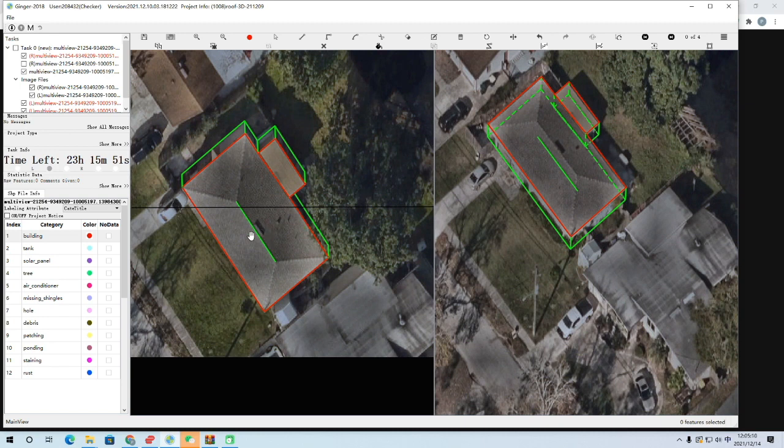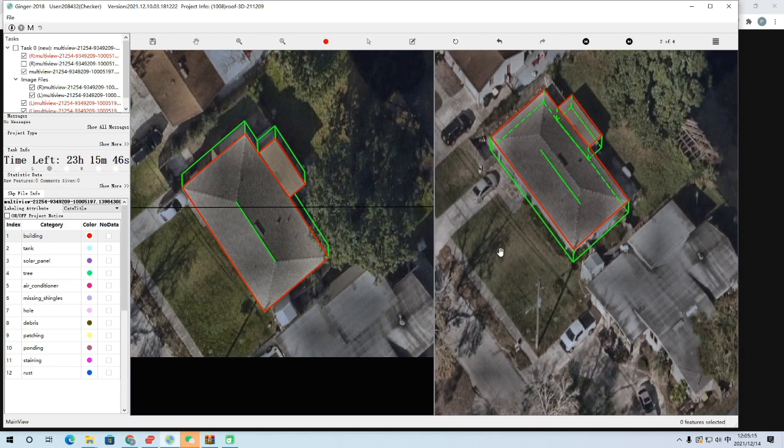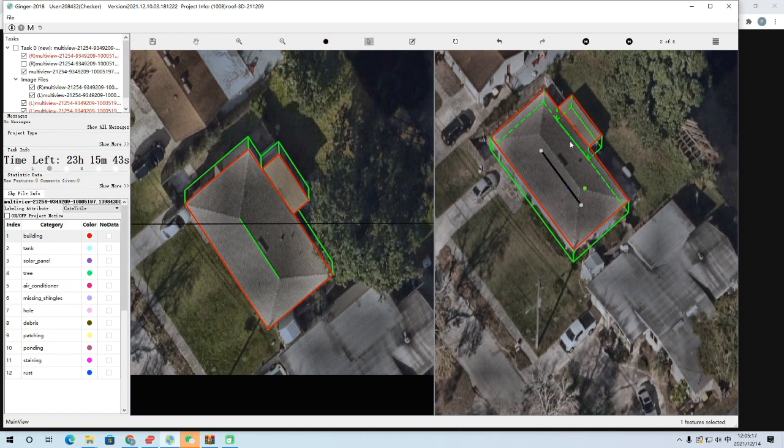Now after you draw the assist line for the roof ridge on the left image, the next thing you need to do is to match. Remember, when we drag the building to match on the right image, you also need to do this step for the assist line on the right image. So after you finish this, select this and move it to match on the right image. I will repeat again: the match on the right image will give the assist line 3D height information.